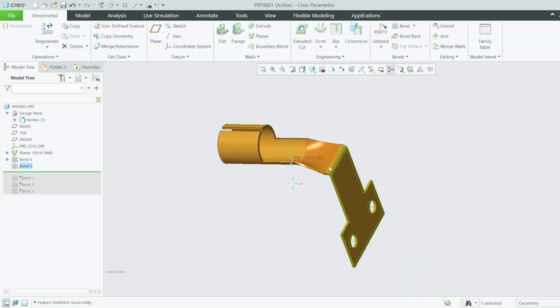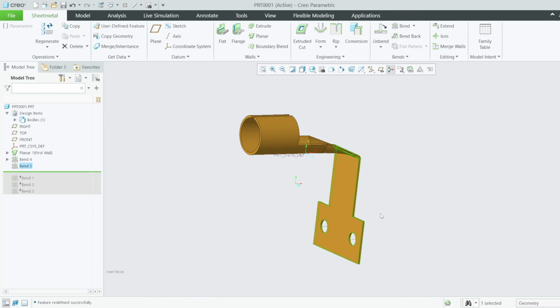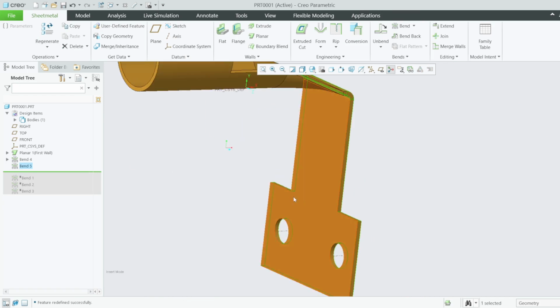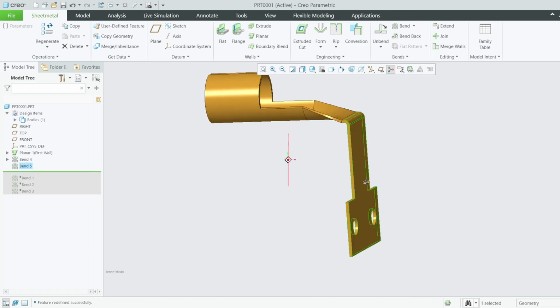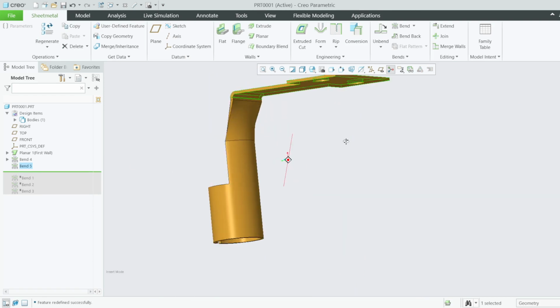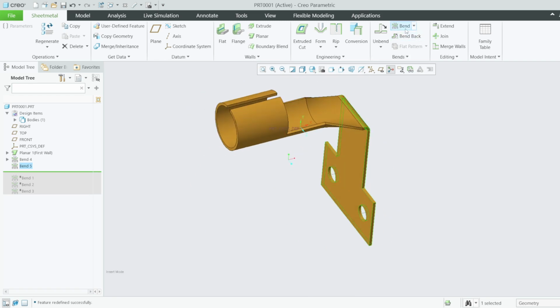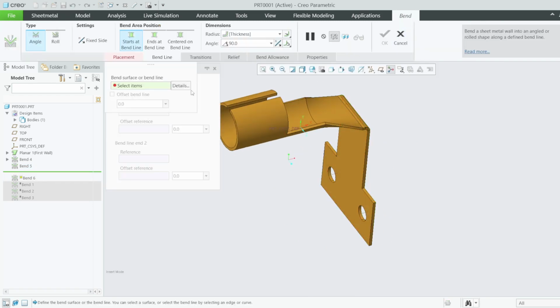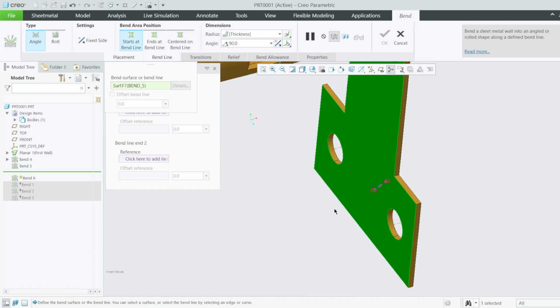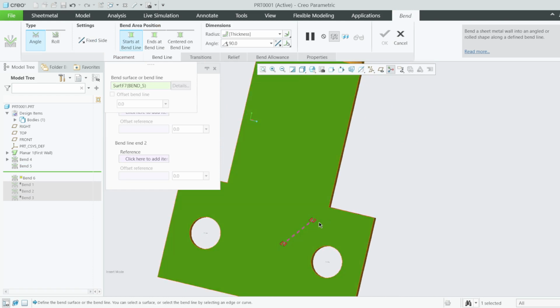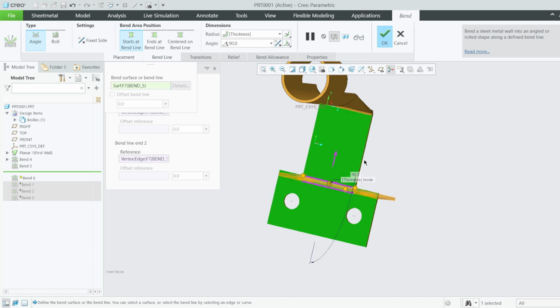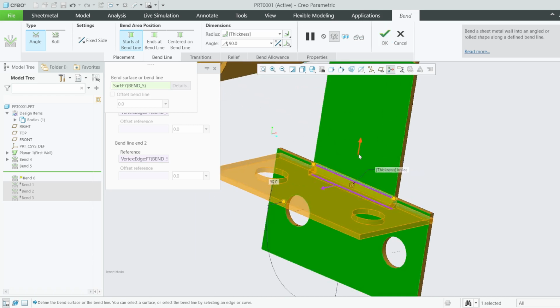Okay. Yeah, then lastly we need to decide to bend the front or back. Yeah, we need to bend the front. You go back to bend, you select this surface. Now remember in my last video we said these draggers here, you can either attach to an edge or a vertex, like that. When you attach to a vertex, it becomes predefined. You don't need to define the values.